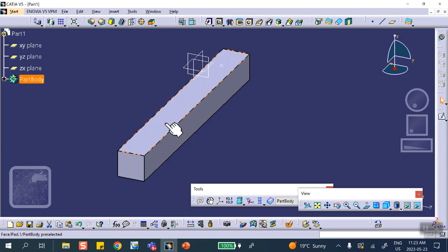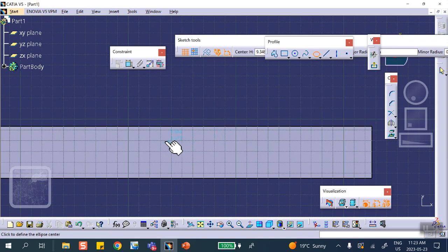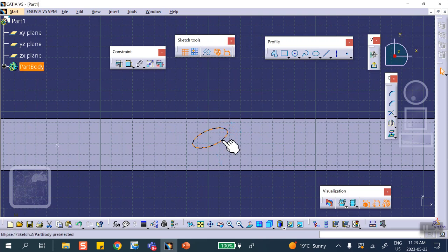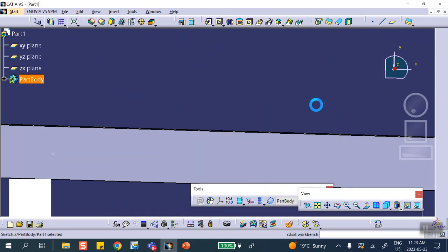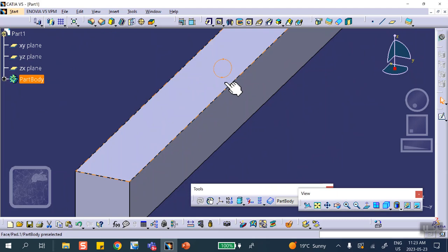And then I want to create a little patch here. So for example, I can say on that face sketch, once again, what do we want here? Ellipse? Okay, here's an ellipse. Where was that point, by the way? The point is on this side, right there. Is that good? Exit. Now, although there is an ellipse on that, in order to create a patch here, we need to put a surface on it. And there are other ways to do it, of course.